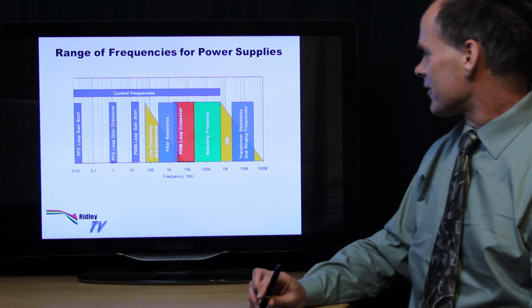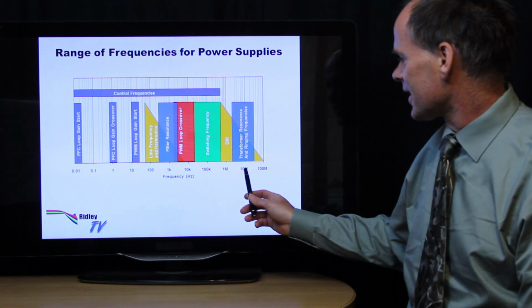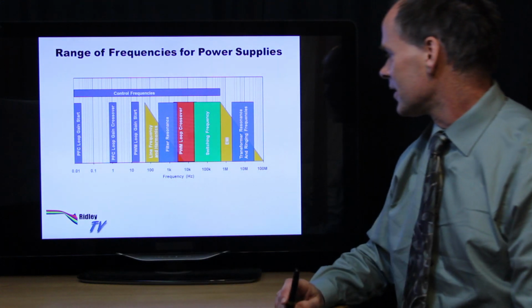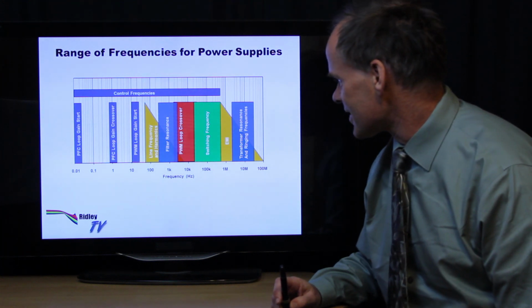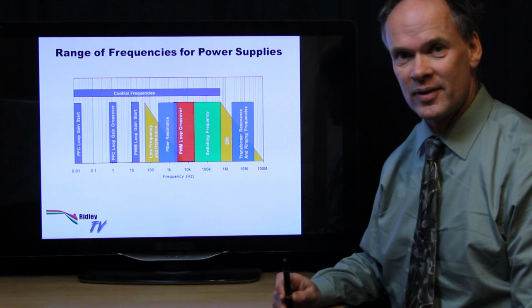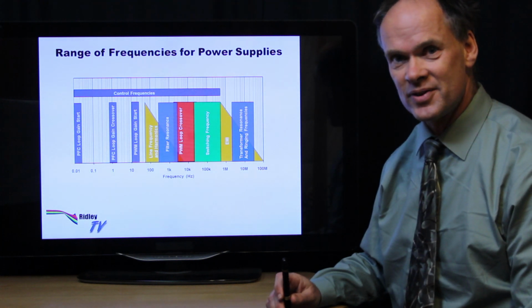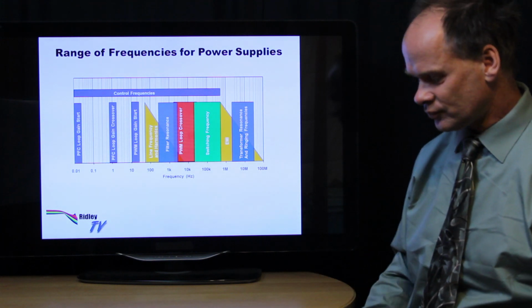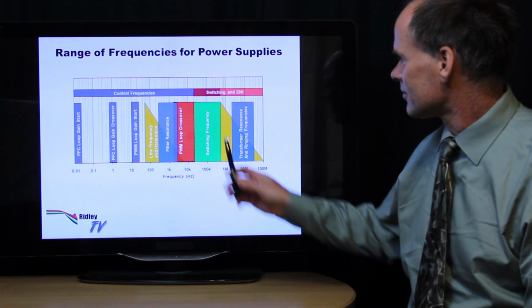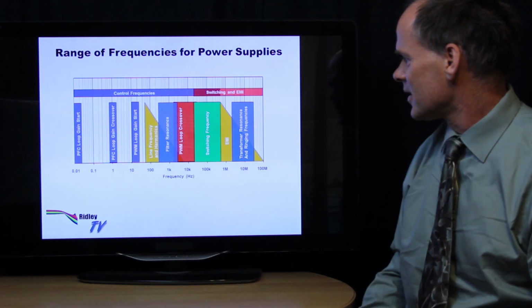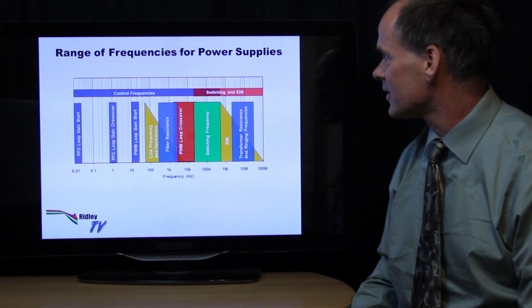So to conclude here, our frequency range goes from in excess of 10 megahertz all the way down to 0.01 hertz. And how many decades is that? That's 9 decades of frequency that we have to track with our frequency response analyzer when doing frequency response analysis of our circuits. Just a summary there: this is switching EMI, and these are the control frequencies that incorporate that full range.